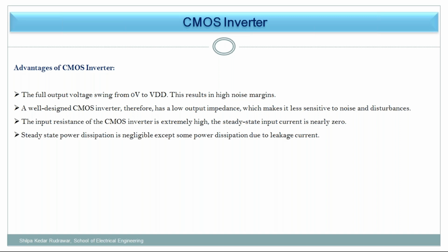So it is a normally off switch, the enhancement MOSFET, used for switching purposes. In digital circuitry, CMOS circuitry, everywhere we are using MOSFET for the switching purpose only. That I also cleared in the previous lectures. We are not using it as an amplifier or anything else, but just as an on-off switch. On-off purpose means, as you know, that the MOSFET works in three regions. First is the cutoff region, second is the linear region, where the current increases with increasing voltage VDS, and third is the saturation region, where the current is maximum.